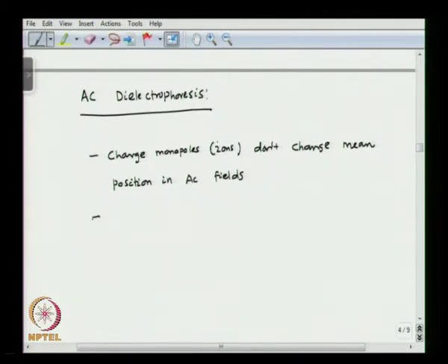Okay. Now the second advantage is that when we talk about the electrodes that we use to achieve dielectrophoresis, we know that when we have a charged surface and a liquid that has non-zero electrical conductivity, it will result in forming what is called the Debye layer. Okay. So in case of DC dielectrophoresis, we have a permanent Debye layer forming over the electrodes, which is not a good sign for the dielectrophoretic force to continuously occur for a longer time. And by going for AC dielectrophoresis, the permanent Debye layer formation on the electrodes is prevented, because there is always a change in the polarity in each cycle. So there is not enough time for the Debye layer to be consistently there for a longer time.